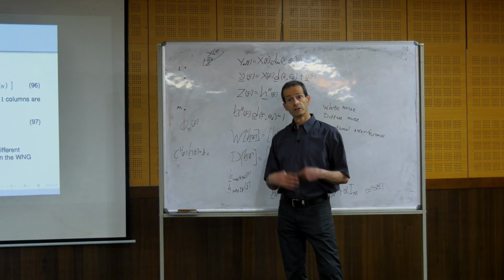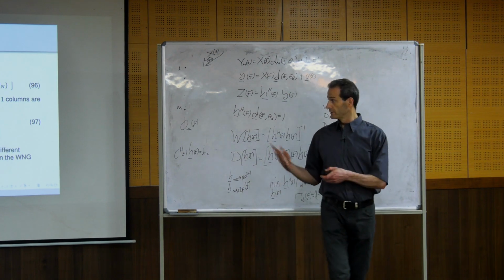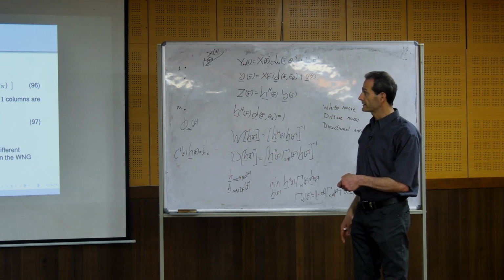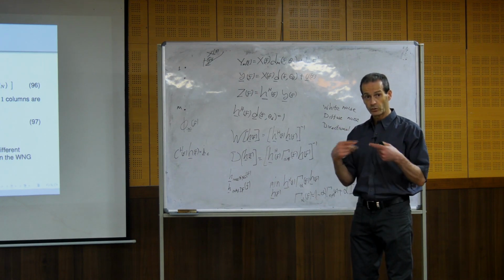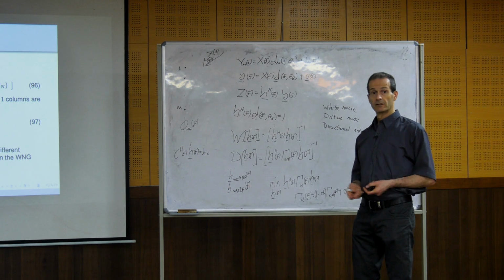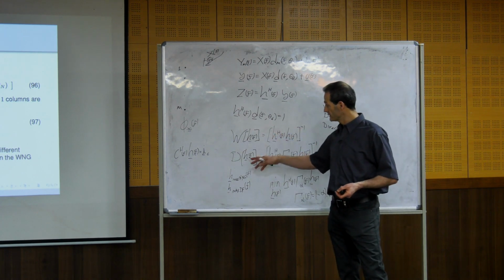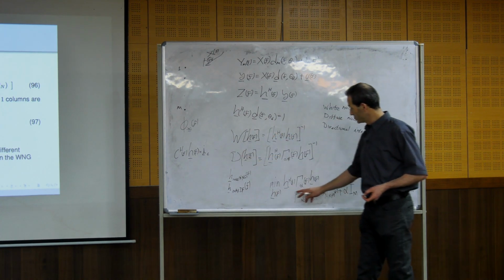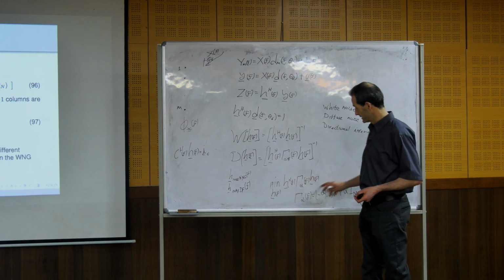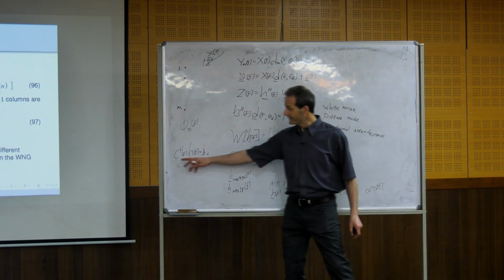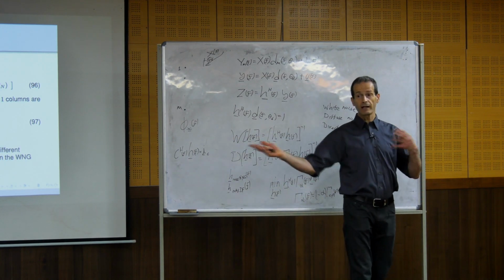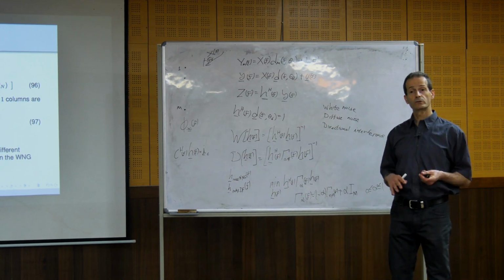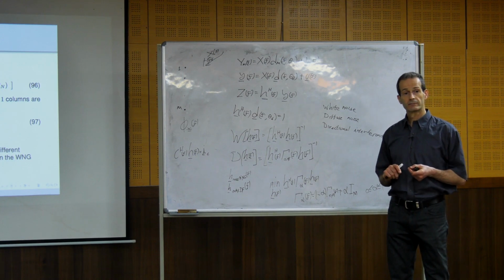Or if we want the beamformer to be robust, robust to what? Robust to thermal noise, we can try to minimize this under these constraints. See? Everything that we want to take into account, we can take into account.